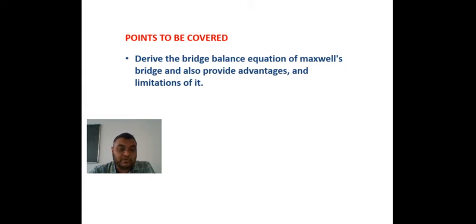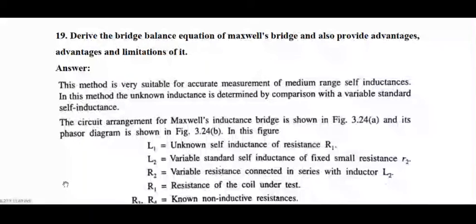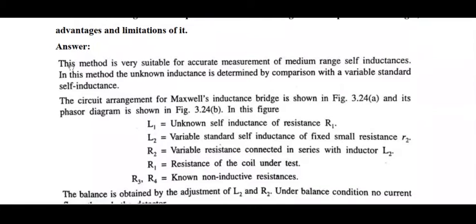Okay, so we will start this theory. So let's begin. Students, today we are going to learn about the bridge balance equation of Maxwell's bridge, and we will also discuss the advantages and limitations of this. First of all, this method is very suitable for accurate measurement of medium range self inductances, and in this method the unknown inductance is determined by comparison with a variable standard self inductance.